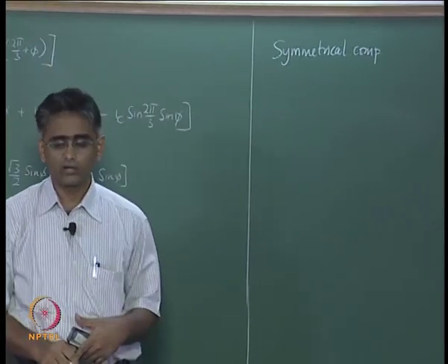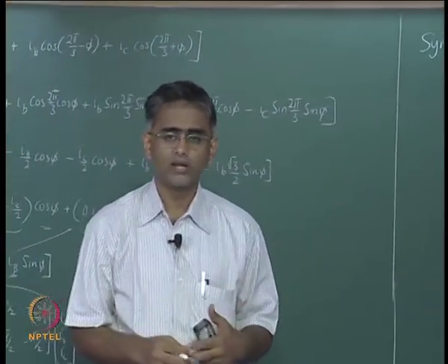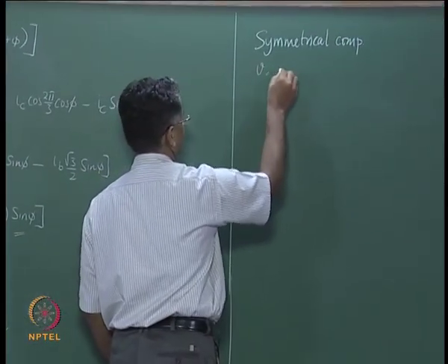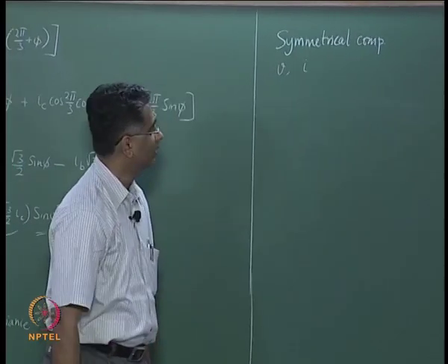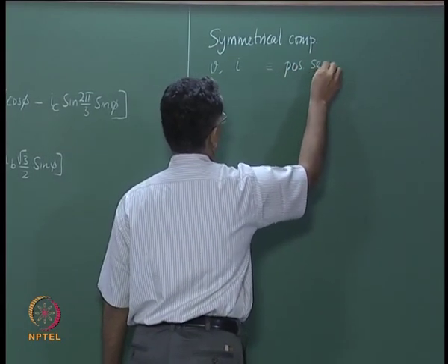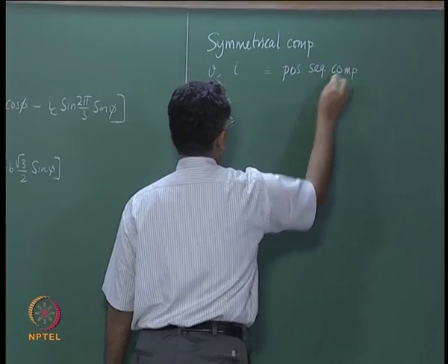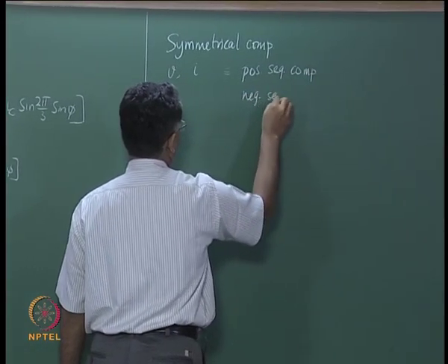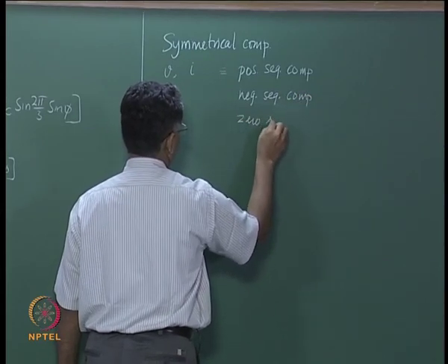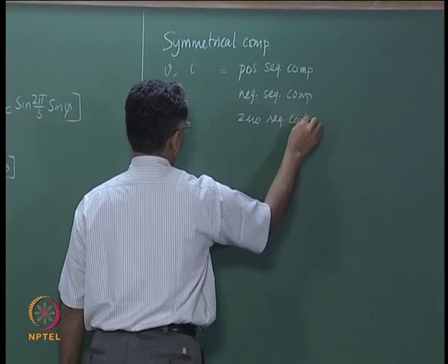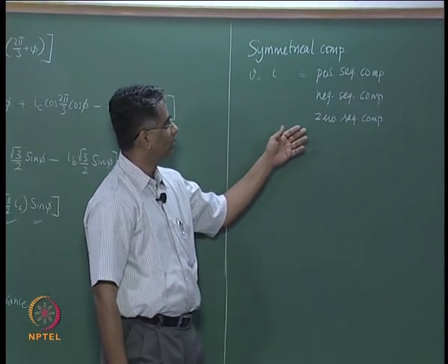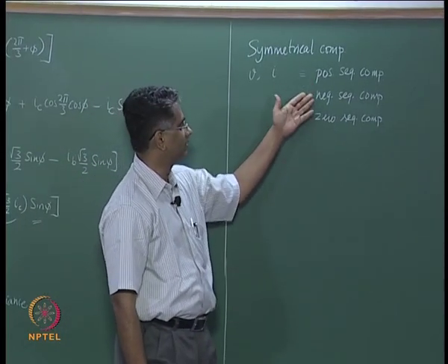The idea of symmetrical components is that any unbalanced 3-phase system of either voltages or currents can be resolved into a positive sequence component plus a negative sequence component and then a zero sequence component. Now you may remember what these 3 sequences are.